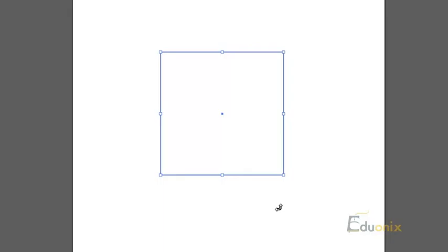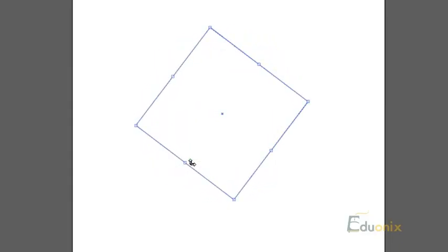It's all going to rotate if you're holding it outside. And remember, this is with transform activated, shortcut key E. So if you start rotating this, it'll rotate. And if you start rotating this while holding in Shift, it'll rotate according to the constraint angle, which is 45 degrees like we just set up.